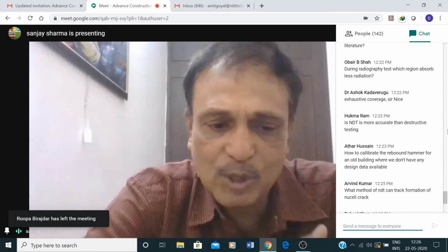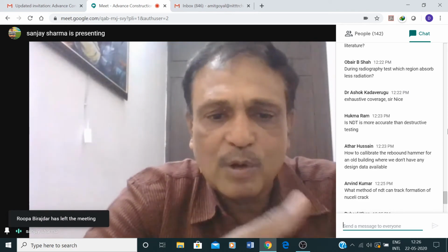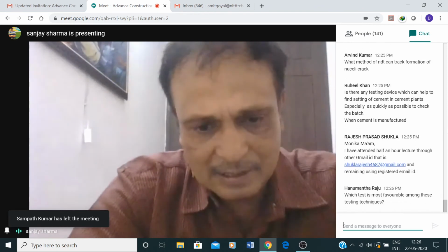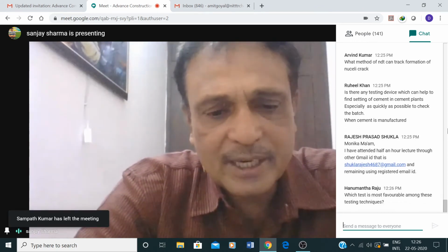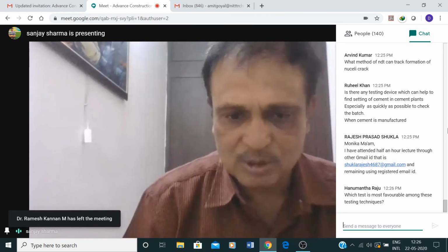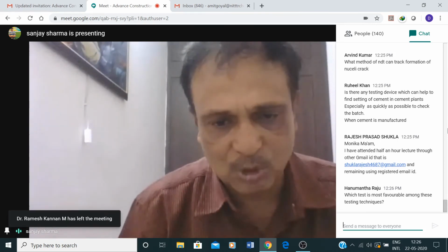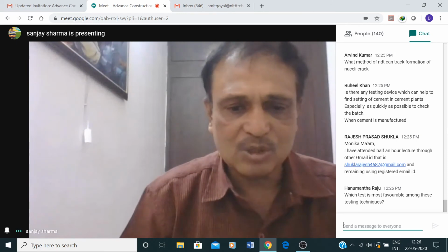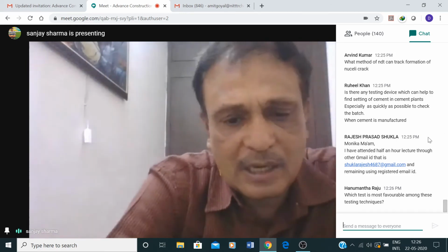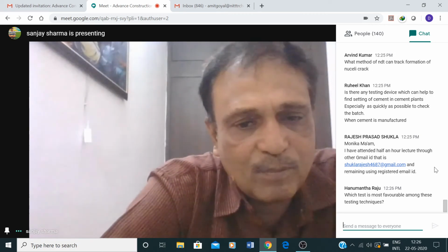If it is beyond 15%, we have to agree that then we will go for UPV test, or you will go for core cutting test. If the core cutting test again does not achieve the desired values, then we will say okay, demolish or strengthen that thing. So that way, interpretation of the NDT or test is very important from that point of view.